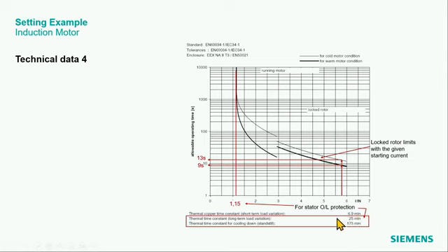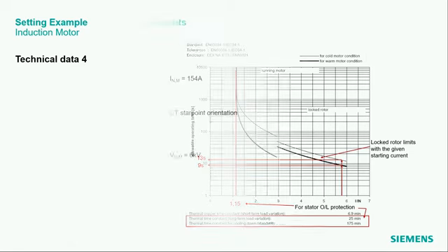And then there's one, if the motor is not running at standstill, then you see this is much higher. The cooling down time constant is much bigger than the time constant when the motor is running, because the ventilation is missing here.